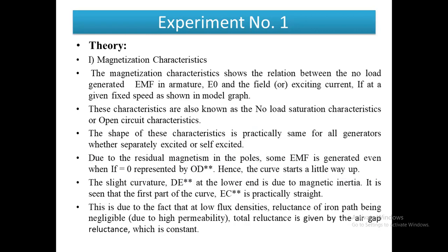Do you know that the open circuit characteristics, that is magnetization characteristics, give a relation between the no load induced EMF in the armature, E0, versus field current IF. We have seen these characteristics while studying the theory. The no load induced EMF is plotted on the y-axis, and the field current is plotted on the x-axis. Now this curve will be obtained like this.